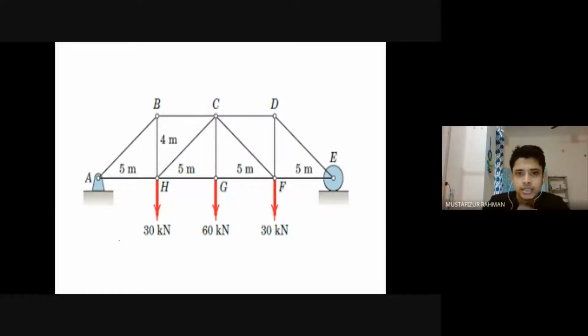Now coming back to the truss system, we will know whatever the external load is, or we have to find it out, for the purpose of designing the truss system or the structural system. Whenever the load is coming, for example, if this is a truss system and the load is coming here at the bottom chord, then maybe this will try to go like this, because the load is in the direction of gravity, and therefore in these members there will be tension force.